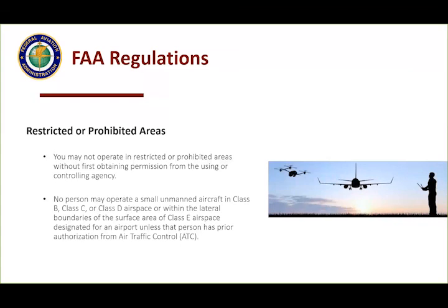There is talk. Stuart, I apologize. This is Dave here. Yes, there is a program by the FAA called LAANC that has been designated out to a lot of different companies that have software apps, and it's designed so that it allows you to create an account and, as they refer to it, gain near real-time authorization to fly in controlled airspace that you need to get authorization from. Though you'll find a lot of airports are not a part of that system, and I'm based here in Maryland, and none of the airports here in Maryland are a part of the LAANC system.